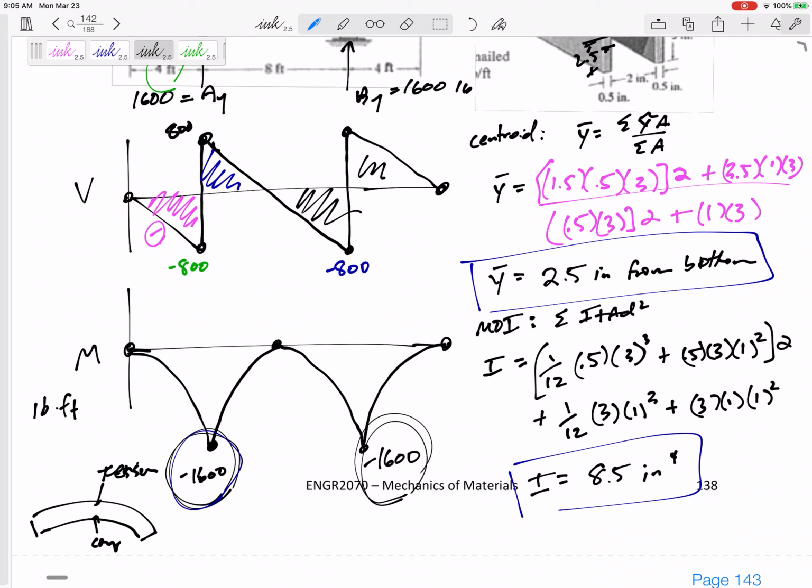You can think about where we started this chapter with those 3 lines. If I had a 4-inch line here, a 4-inch line here, a 4-inch line here, this green 4-inch line on the bottom would get compressed to maybe 3 inches. Or imagine putting your finger right here. It would get pinched, right? It would get compressed. So a negative moment is like a frown. And with that one, there would be tension on the bottom, compression on the top.